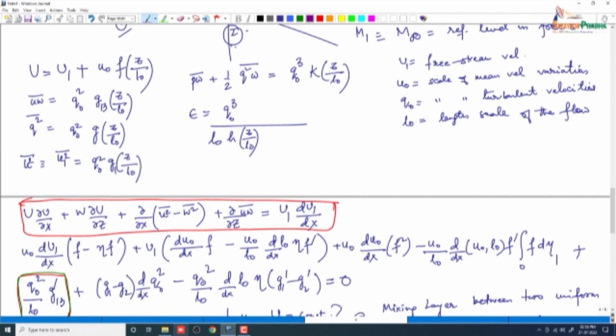Now, non-existence of symmetry may be a natural outcome of the flow. So although there is local equilibrium and self-preservation is possible, it may not be axisymmetric, right? What we're trying to say is that the flow itself, in order to be in equilibrium, actually becomes non-axisymmetric, and does not enforce the axisymmetry.